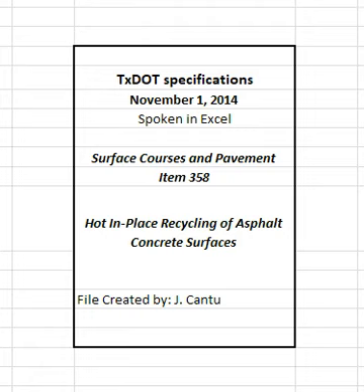3.1.1 Pavement preheaters. Supply pavement preheaters capable of uniformly heating the existing pavement to a temperature high enough to remove excess moisture and allow dislodging of the material to the specified depth, while minimizing the fracturing of aggregate particles. Equip heaters with an enclosed or shielded hood to prevent damage to adjacent property or vegetation. Ensure that the heaters overlap the completed adjacent lane by a minimum of 6 inches to create a hot bond at the longitudinal joint.